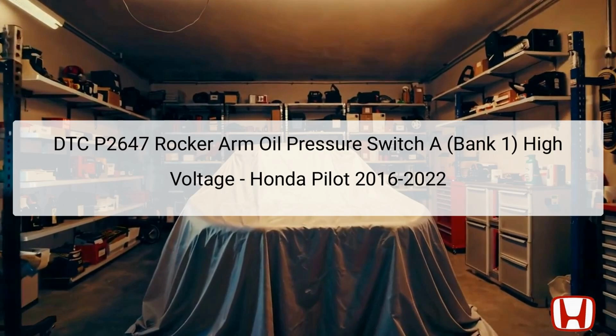Welcome to this troubleshooting guide for DTC P2647, which indicates that the rocker arm oil pressure switch A on bank 1 is experiencing high voltage in its circuit. This issue can significantly affect engine performance and oil pressure regulation. The rocker arm oil pressure switch A plays a vital role in regulating oil pressure to the rocker arms, which are essential for valve timing and overall engine functionality.